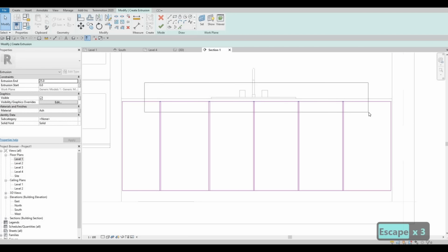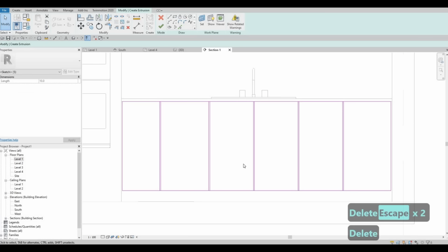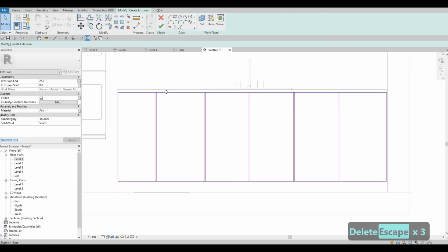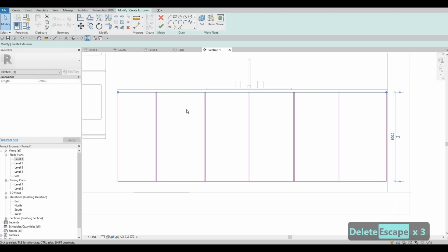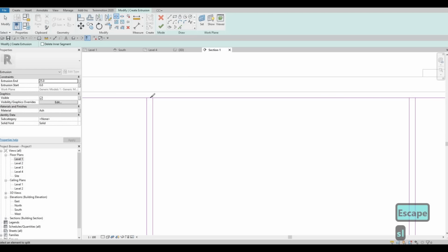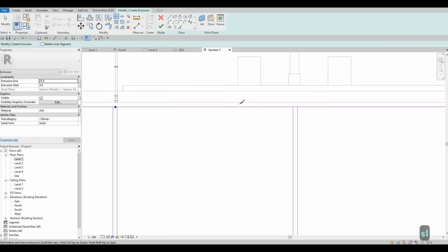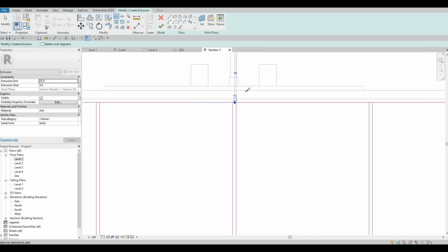Select the lights at the top, those small ones, and then here I'm gonna nudge it a little bit at the top as well to give it some room. And then now type in SL, that's split element. We need to split element all of this.